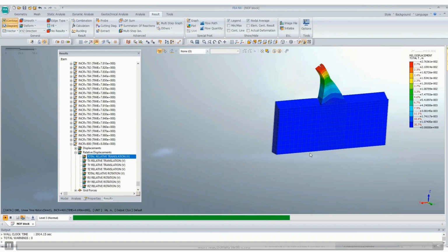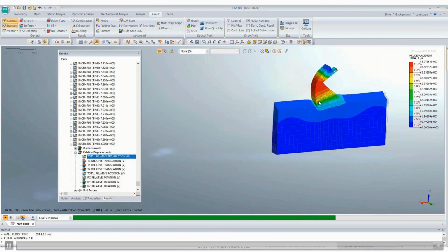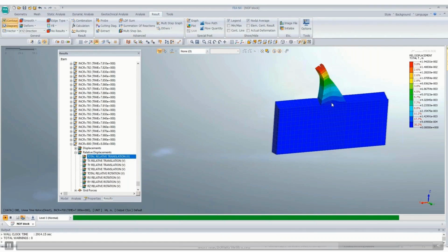There I'll paste them, and then we will plot factor of safety against sliding versus time period, and we'll check the minimum and maximum values of the principal stresses in the foundation block at the foundation, and normal stresses in the interface element to check how much